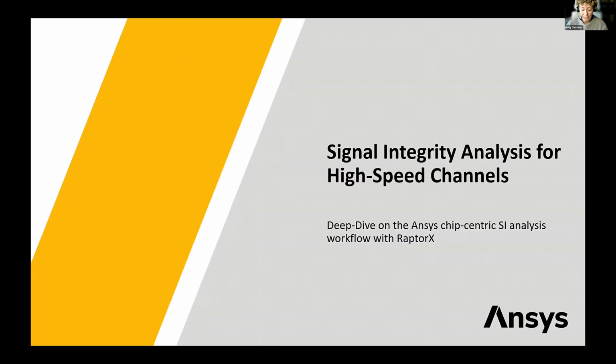The benefits of 2.5D ICs come with trade-offs, and 3D ICs, of course, including the need to confront new and exacerbated physics. And those physics were not something that monolithic chip designers had to worry much about. They were able to model them and make up for them with some margins. Now in 2.5Ds and 3D ICs, they are much more critical. And one of the most critical of these new concerns is high accuracy signal integrity sign-off for the interconnect on silicon interposers.